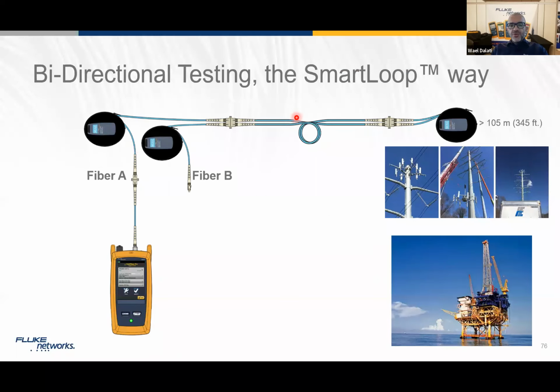Let's say you have your OTDR, you have your launch, and you have a link. And at the end of the link, normally you put a tail fiber. But what we ask you now is to connect the tail from one core to the second core in your link, because in enterprise we normally use duplex cabling. So connect the second point of the launch cable to the second core and add an additional drum of cable at the end of fiber B. So we have fiber A and fiber B.